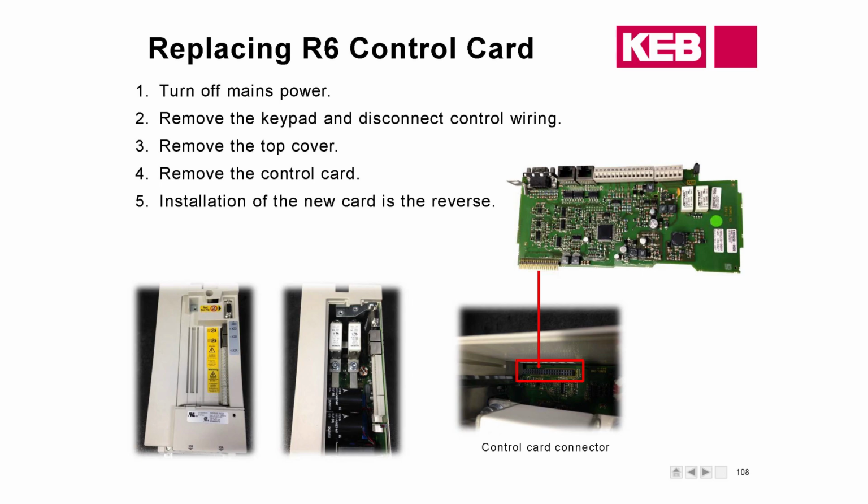Here are your 2 DC bus fuses. And then the control card is actually going to fit in there vertically. These pins here are going to go into this connection strip down here. You need to make sure that all these pins line up, that you're not off by one.